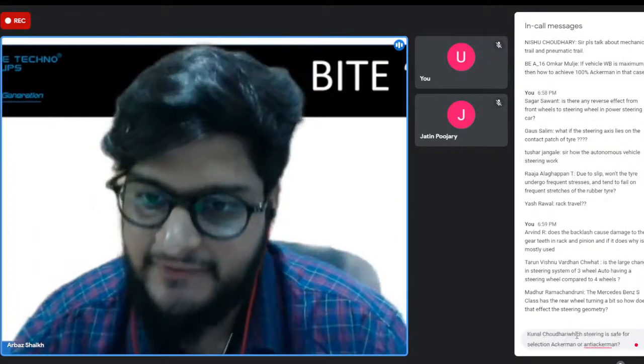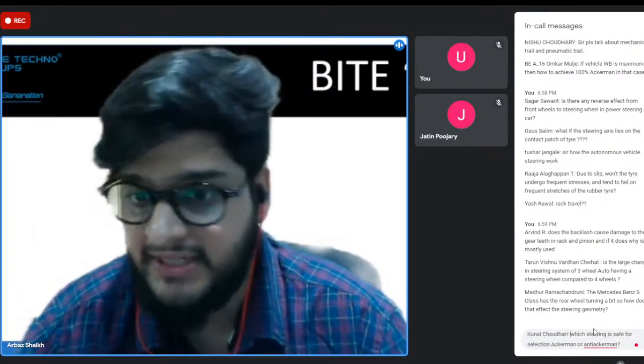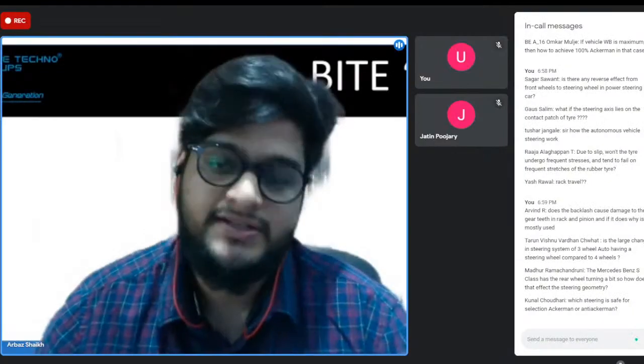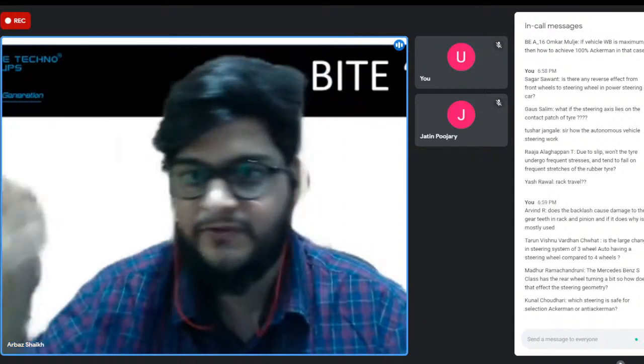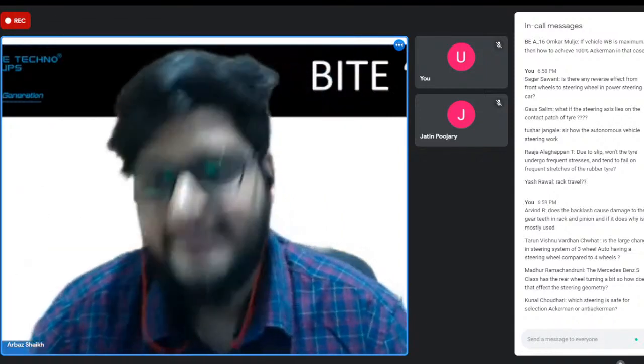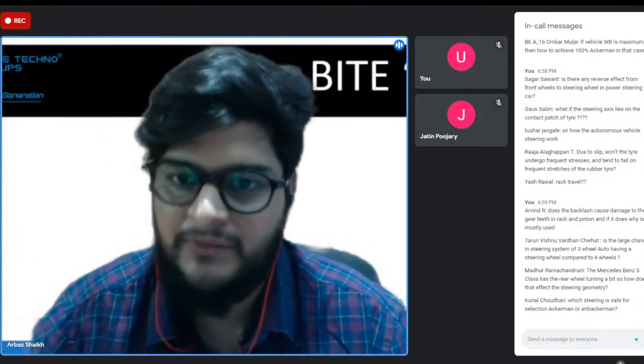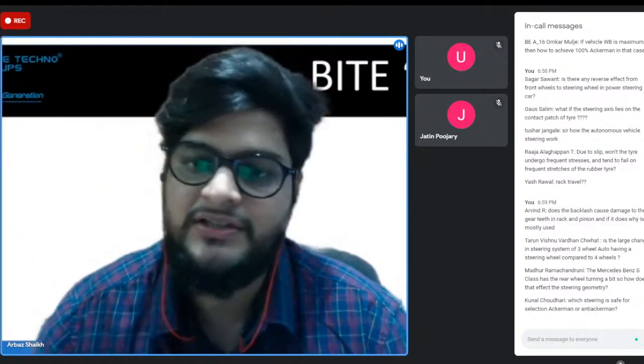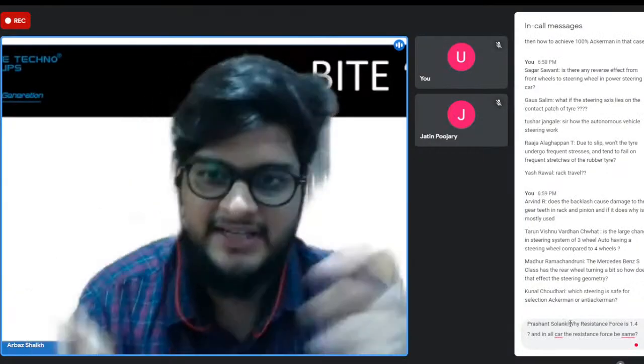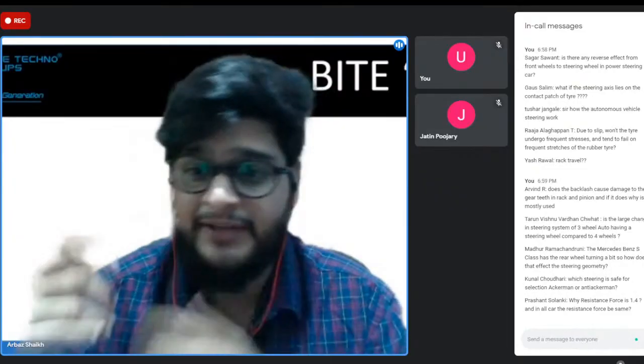Sagar is asking, is there any reverse effect from the front wheel to the steering wheel in a power steering car? So you're asking if there's a force transfer from the road wheels to your steering wheel in power steering cars. Yes, there is, but the effect is very low. Whenever you're driving a power steering car, you can feel the bumps and all those things in your steering wheel. Whenever you go through a bump, you'll feel the steering wheel turn in your hand, but it's very low compared to a manual car.